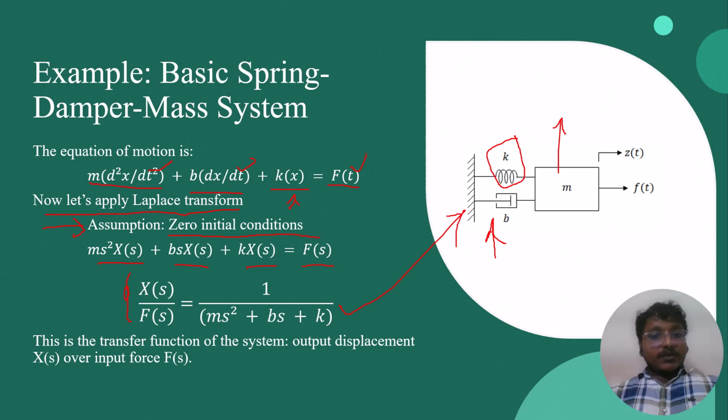Then according to this, whatever we need to control, we can easily get from the equation. We can get the numerator and denominator factors, so we can easily see which one needs to be considered and which one needs to be controlled. This is how the transfer function is obtained with respect to displacement and input force.